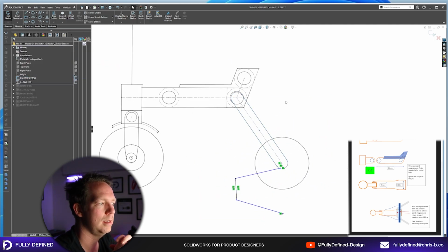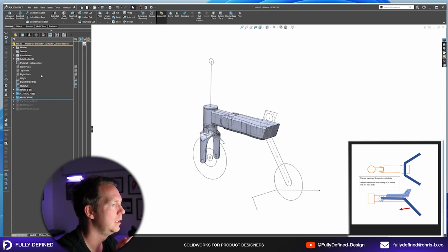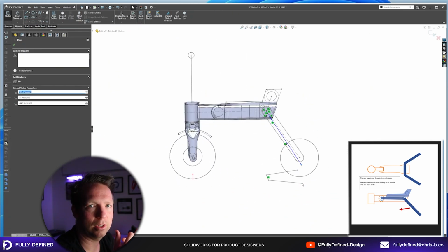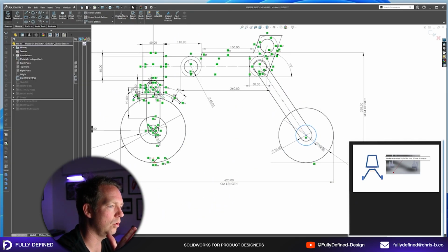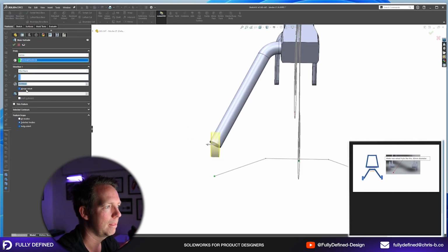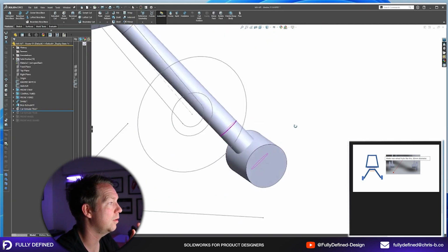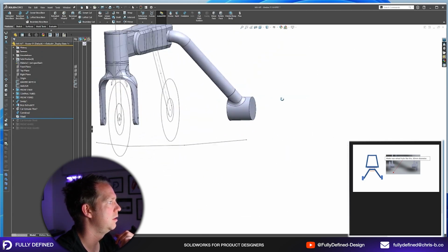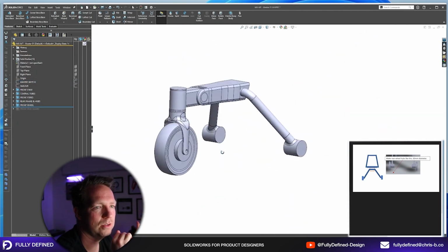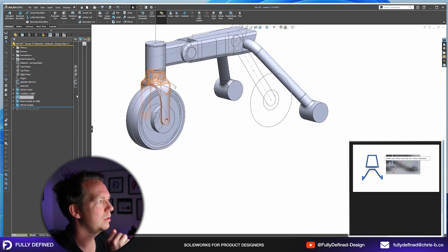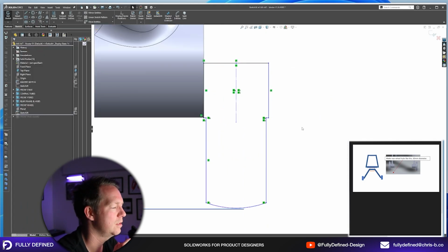That point might be the end of a working session for a couple of hours, or the end of the brief from a client for that phase of the work. So I might go through and get all of that geometry done, and then I can go back to my model, and that's when I can clean up my model. And you can see what we've got now is a very clean feature tree where I've got a master sketch and a second sketch at the top of the tree, but then everything below is in folders, and I've repositioned and reordered some of those features so that they make sense.